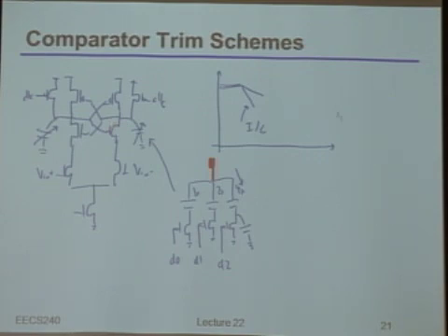The reason that's bad is that even though we may not care about linearity on the net, if you think about it, if I fix the two endpoints, meaning this is what I'm supposed to be applying in terms of offset versus code on one end, and this is what I want to apply on the other end, and what I'm interested in is the largest step size you get in between, well, the way to minimize that step size is to make this line perfectly straight.